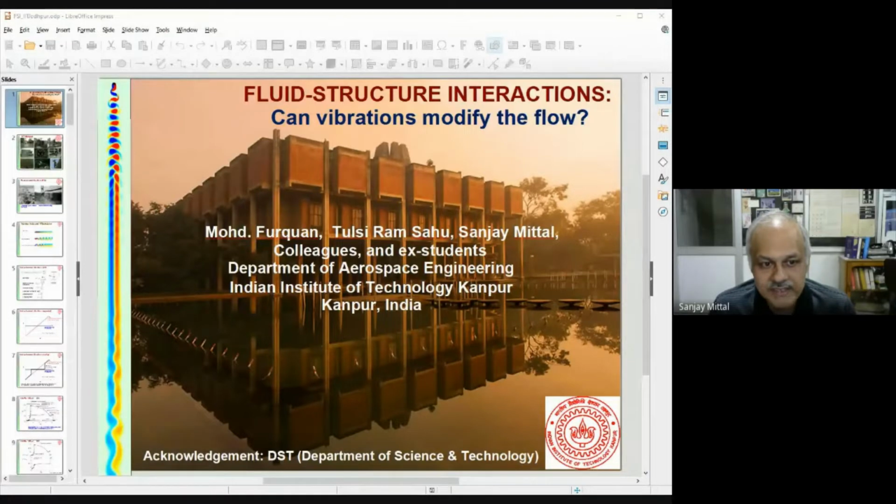In this kind of configuration, air could come from any direction. The lesson learned is that you should not only test the standalone structures, but the interference effects are also very important. The next one is the Tacoma Narrows Bridge, which had this galloping response, and you can in fact see a small car on the bridge. Fortunately, there were no casualties. But this problem drew everybody's attention to how important flow-induced vibrations can be.